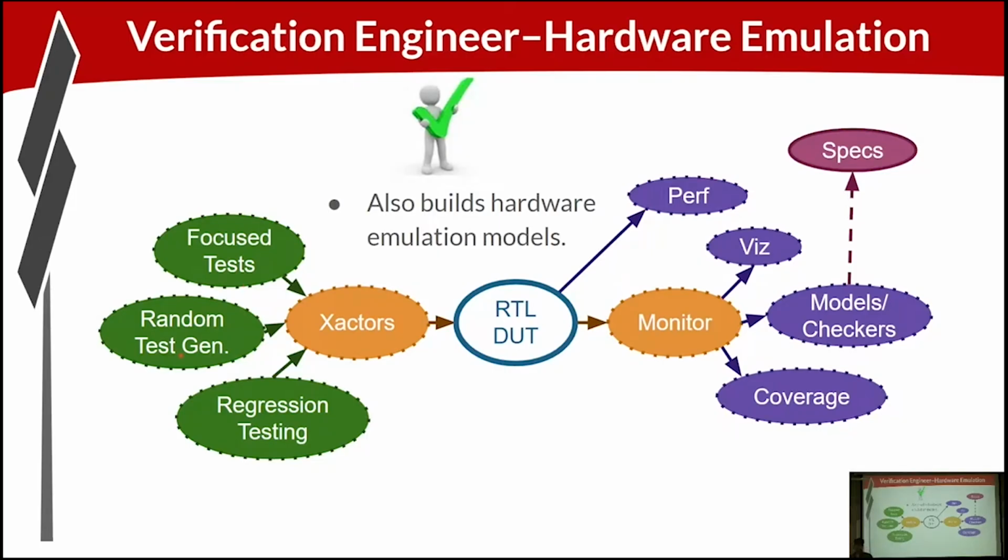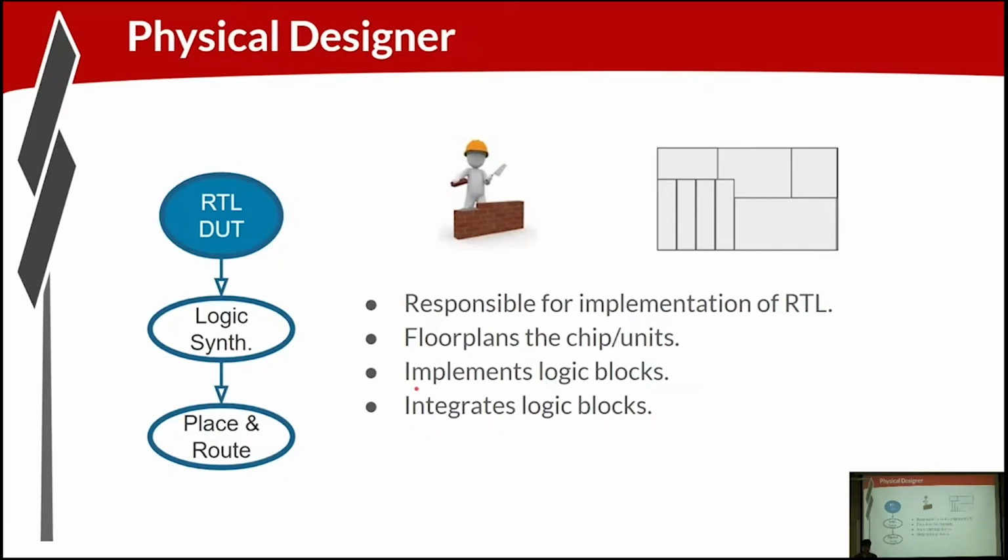Essentially, though, the nature of the modeling kind of fits this picture either way. And so the physical designer, and we're going to come back more to the verification role since it is so intricate, but the physical designer is fed the RTL. They run logic synthesis, place and route. Right? So logic synthesis is coming up with kind of the gate level model, and then place and route is placing the gates physically across the silicon area that's available and connecting up the gates.